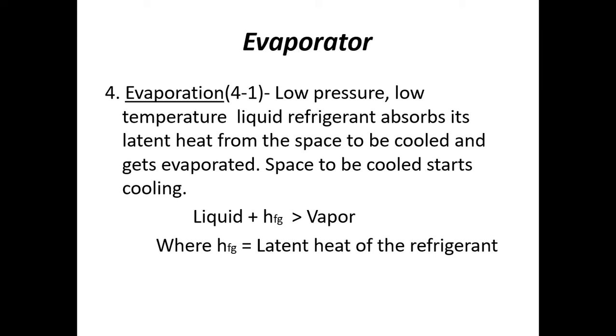Next, you have the evaporator. After expansion you have a lower temperature liquid refrigerant. When this lower temperature liquid refrigerant passes through the evaporator coil, it absorbs its latent heat from the space to be cooled and gets vaporized.